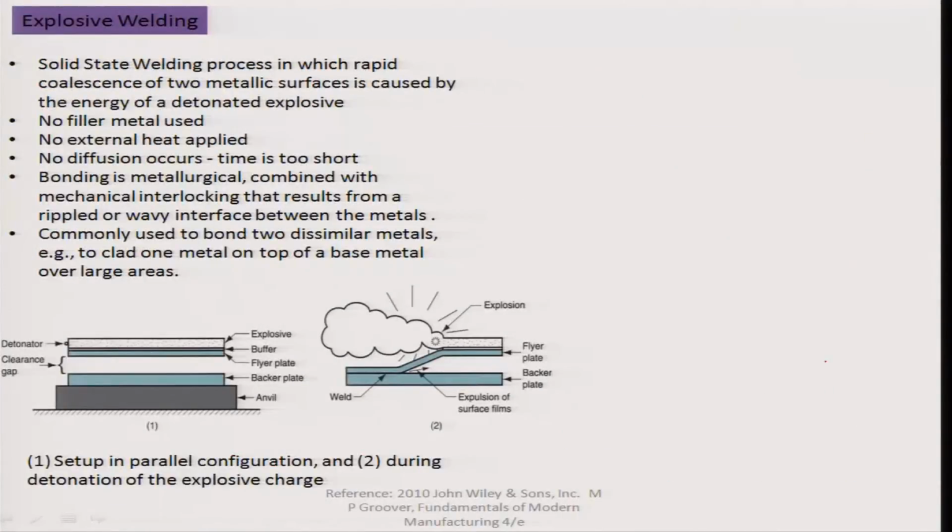You can also have explosive welding, where you can see here there is a coat of explosive on the top layer of one of the sheets, which is placed with some clearance gap with respect to the sheet you want to weld it to. Then there is a sudden area which is exploded, which results in momentum and bending of the sheet, so that a pressure based welding forms. This is again another case of solid state welding. It forms on the surface, and that's how you do explosive welding.